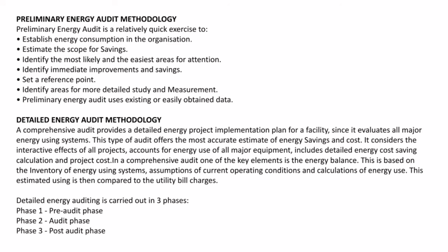In a comprehensive audit, one of the key elements is the energy balance. This is based on the inventory of energy using systems, assumptions of current operating conditions, and calculations of energy use. This estimation is then compared to the utility bill charges.